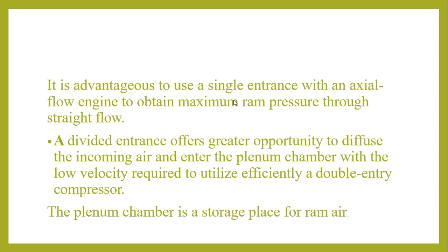And then we have the divided entrance. It offers the greater opportunity to diffuse incoming air and enter the plenum chamber. Plenum is like a storage chamber with low velocity, required to utilize efficiently a double entry compressor.